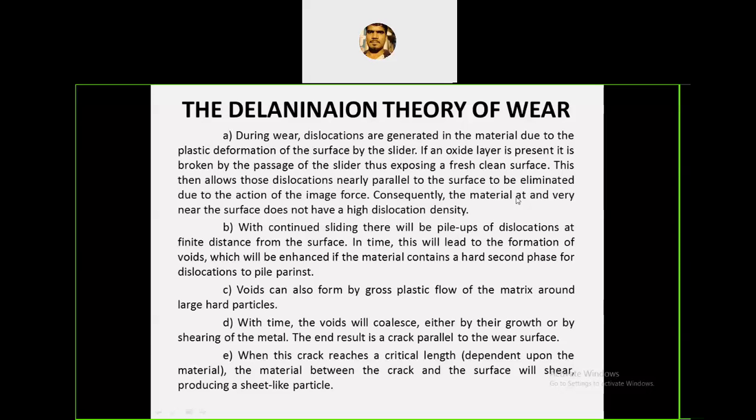When the crack reaches the critical length, what happens depends upon the material. That material between the crack and the surface will shear up, producing sheet-like particles.